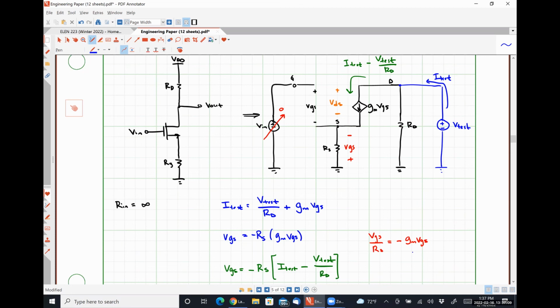And so your suggestion here is that if we had a positive quantity VGS, this would force some amount of positive current through this resistor RS, giving us a positive voltage drop, which would conflict with the polarity of this. I don't see anything wrong with your assumption there.